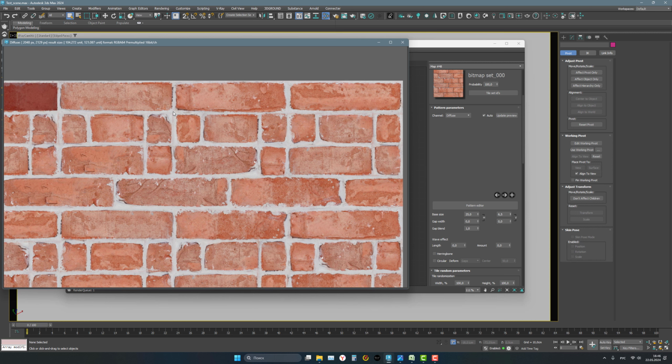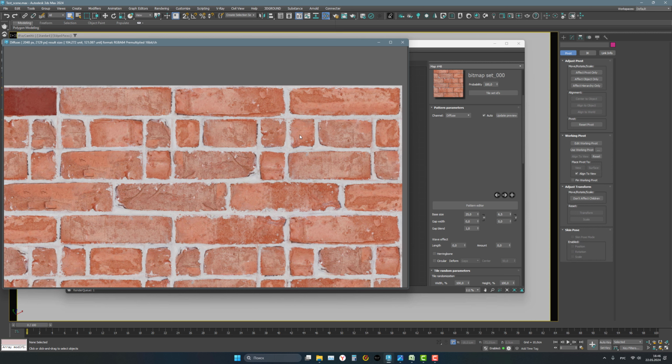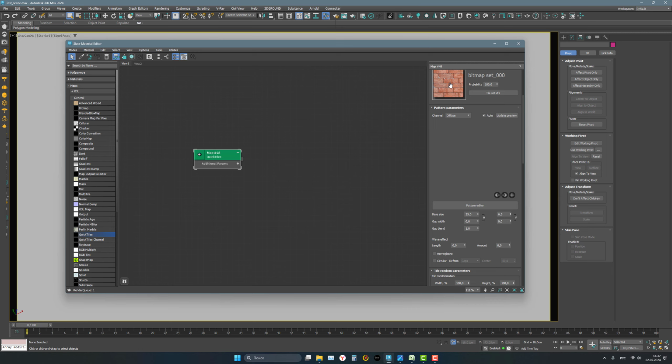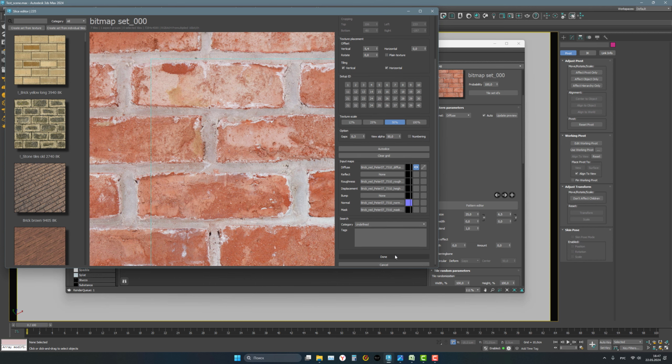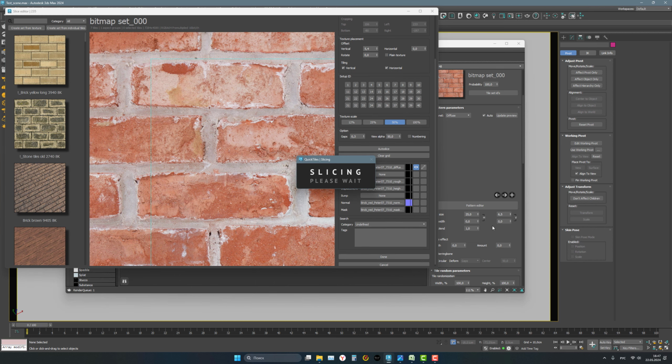This is because, do not forget that the gap also has its own thickness. By the way, when capturing the original gaps, the thickness is set in the gaps parameter in the slicer. And if you use several sets, I will say, going a little forward, then the smallest of all sets will be used, the width of the gaps parameter. Let's go to the slicer and try to change this parameter. Now we have the parameter set to 0.6, let's set it to 0.3. Accept the result.